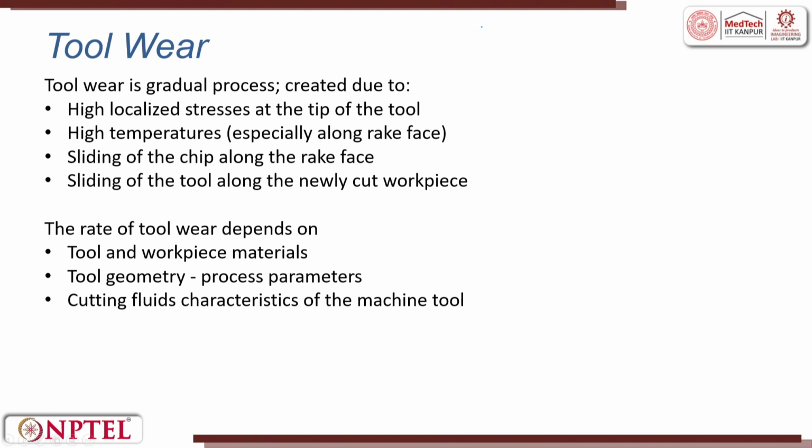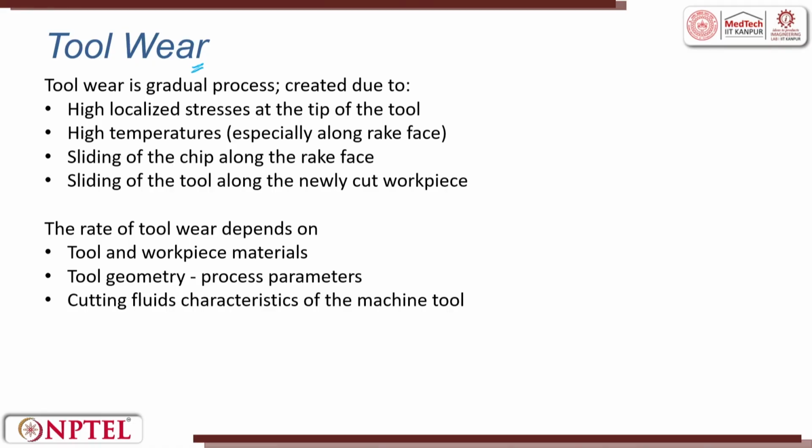So, the final point of discussion is going to be tool wear. Because of the friction, there is going to be a deformation which is happening on the tool. So, now let us try to discuss the tool wear. If the tool wear happens, then the tool geometry changes. If the tool geometry changes, the surface finish that is generated is not good, and the forces might go high.